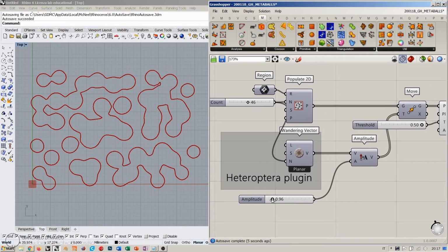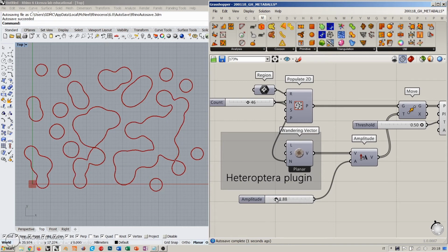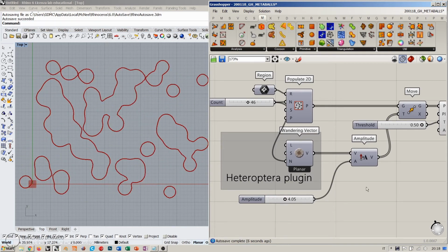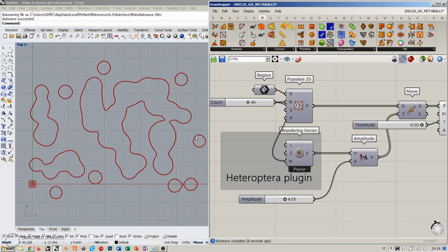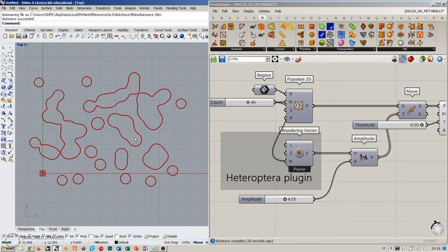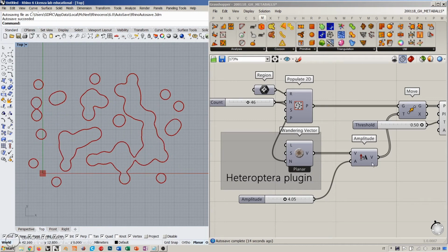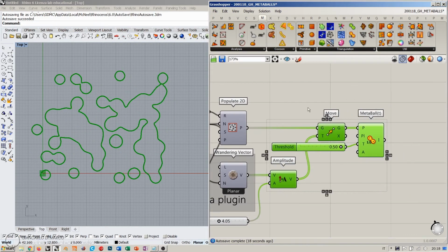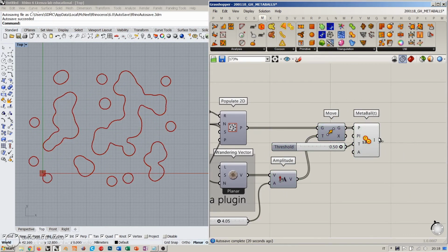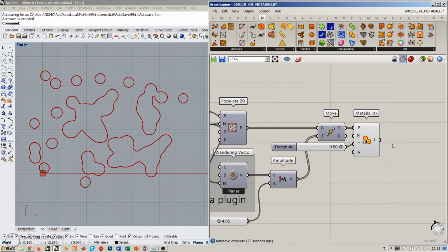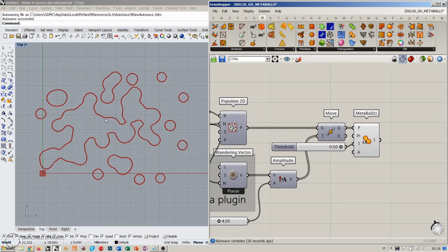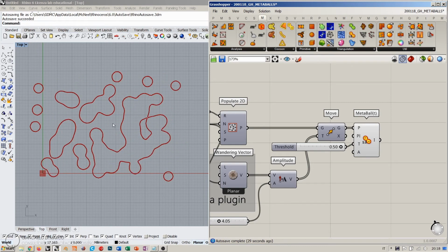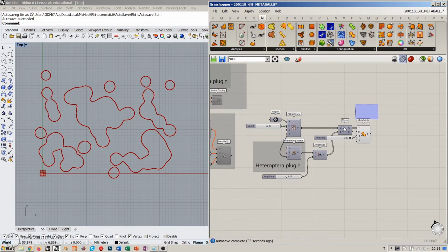Okay, so for example, like this, if I increase these values very much, I will start to have a more randomish behavior for my Metaball curves. Just remember that if you want, you must always smoothen these curves, converting them into Nurbs curves instead of working with polylines, if you want a more natural or organic aspect for your curves. Okay, so very nice result here.